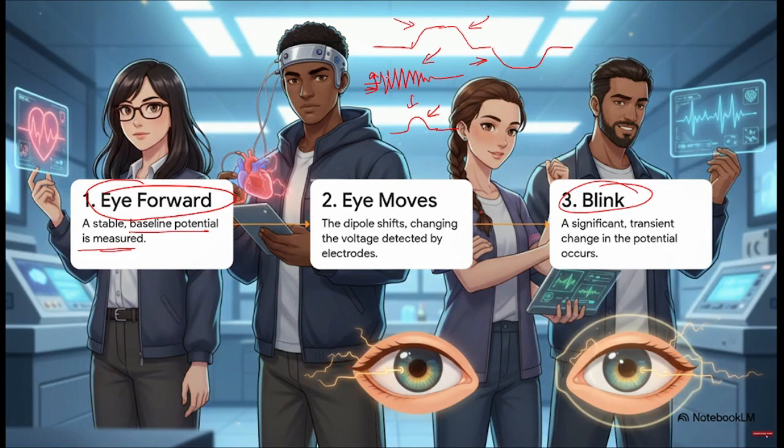So in the EMG signal pre-processing, we collect the EMG signal, square it, and then use a moving averager, and due to that we get an envelope of the EMG signal like this. It is always a positive signal component. From this, we can find the entropy of the signal and the energy of the signal.